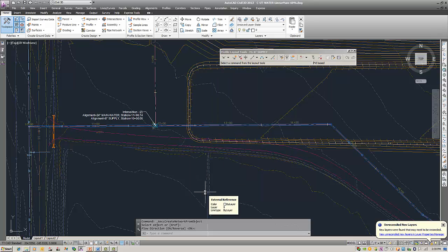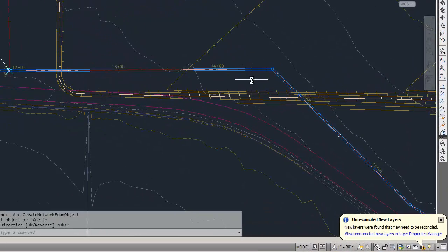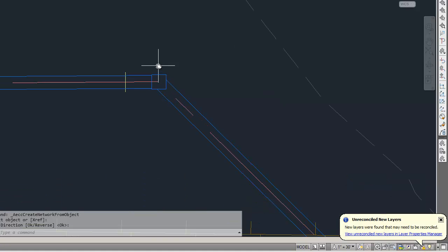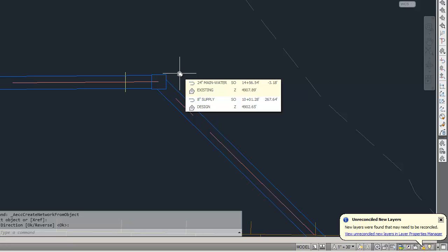and voila, it has selected the particular styles for the pipe. I can see that my double line pipe is in fact in there. All the fittings have been placed in. I'm going to zoom into an area, and that doesn't look like a 45-degree bend, does it? This is where we're now going to come in and start swapping our pipe parts.